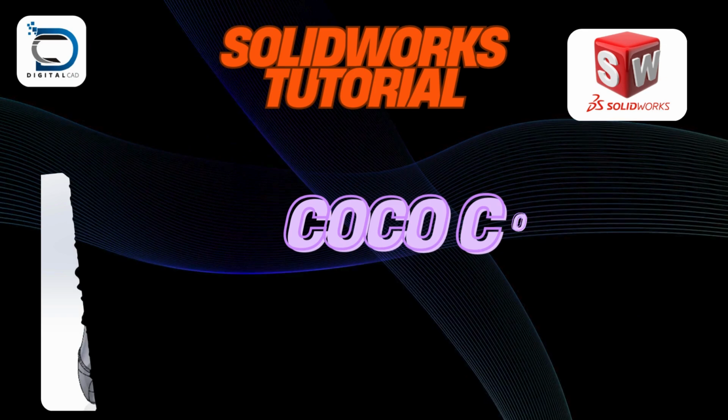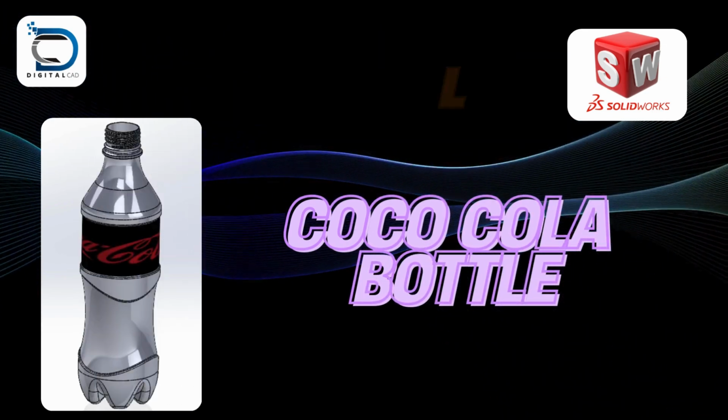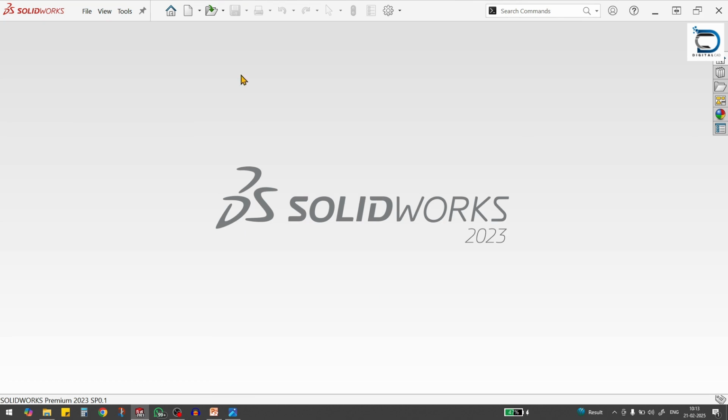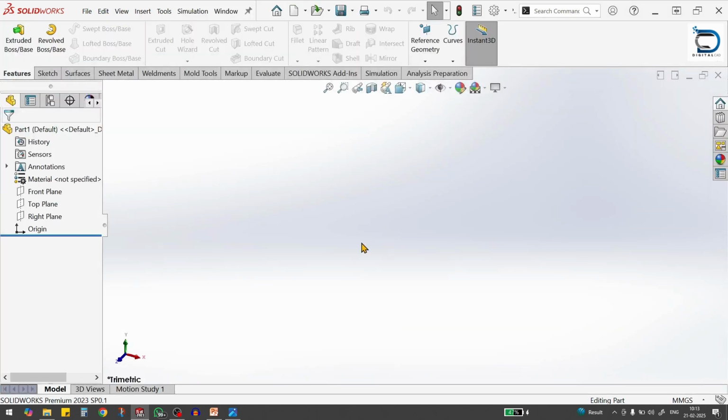Today we are going to create a 3D model of the Coca-Cola bottle in SolidWorks. We are using this 2D drawing to create the bottle. Let's start. Initially go to New, select Part, then say OK. We will create it on the front plane.